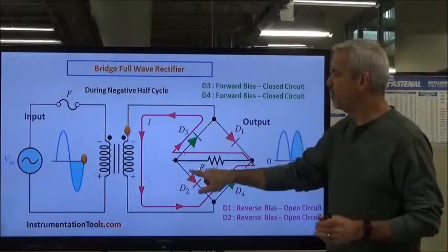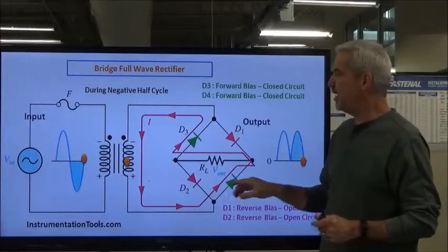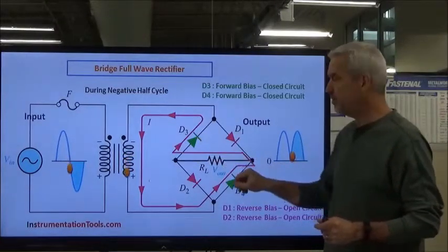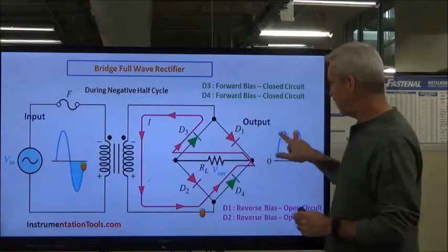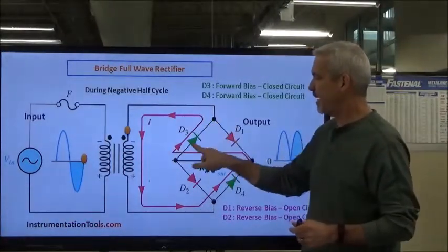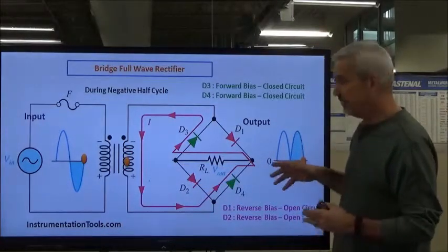We route it through the diodes. And the diodes are configured in such a way that it will allow the first half cycle positive ones to go through and create the first half cycle of DC, and then the second half it will be allowed to go the other way and creates another half cycle of DC.